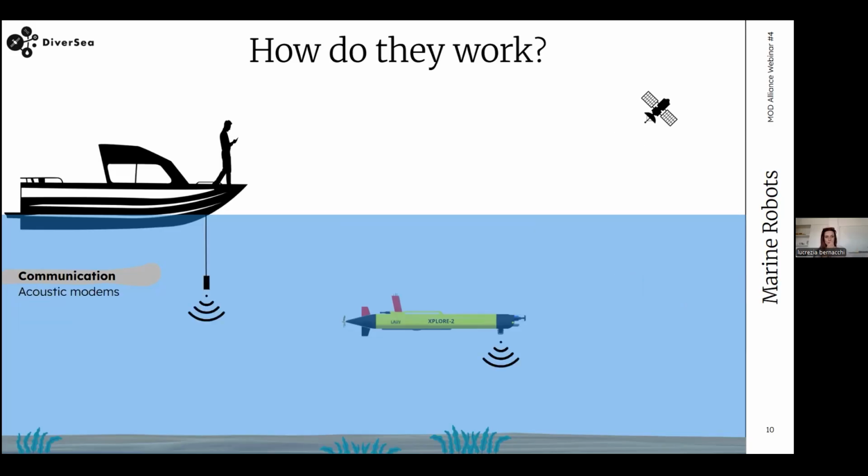So regarding the communication, what we can do is to deploy acoustic modems, if we can, from shore or from the boat, and we can talk with the vehicle with the acoustic modems, because the acoustic waves can travel long distance underwater, in contrast with the radio waves. And of course the bandwidth is not that big, so we cannot exchange a big amount of data, but we can communicate.